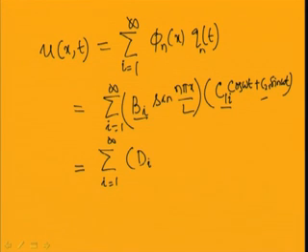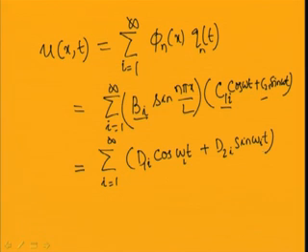So, this becomes d1_i cos(omega_i t) plus d2_i sin(omega_i t), where this omega_i are the natural frequencies of the system. So, this into the mode shapes term also will be there, so this into sin(n pi x by L).